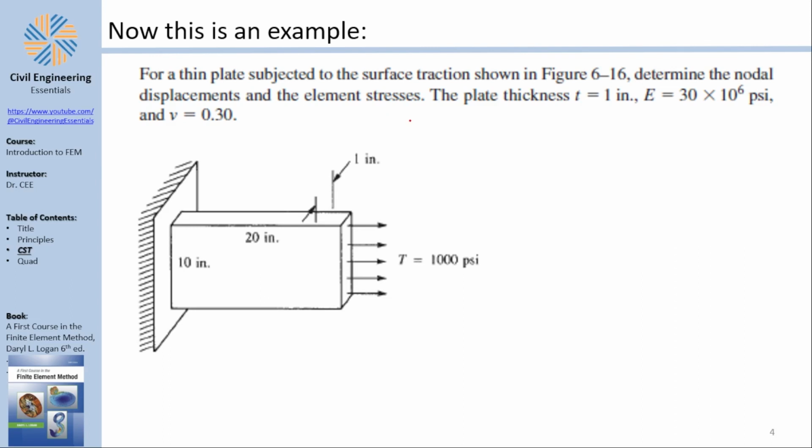Now, one strange thing the book does before that is it shows you one big equation, matrix K, which tries to give you the local stiffness matrix of the CST element directly. Now, he gives you this, but doesn't use it. He still uses the TABDB approach. I will show you that.